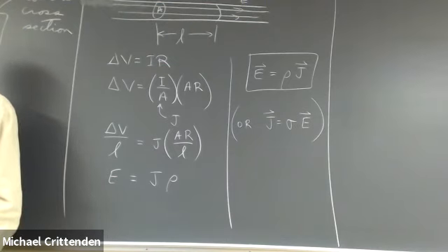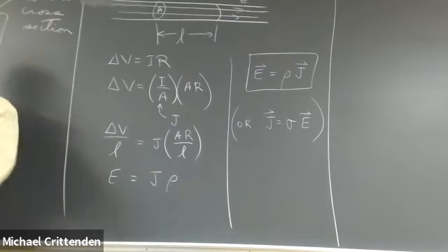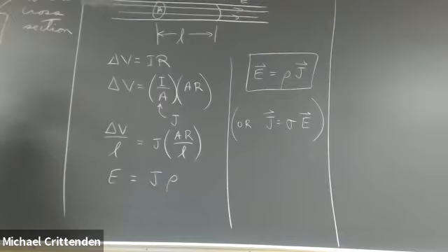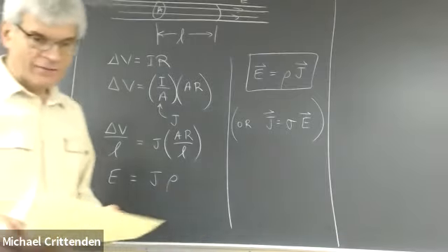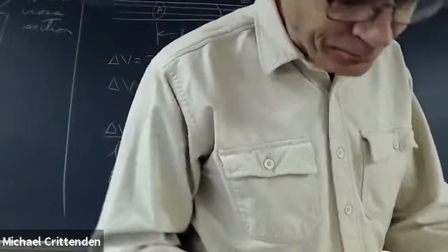Or maybe a more extreme example is something that's not really a resistor at all. A solid state diode is extremely non-ohmic. You apply a voltage to it in one direction and the current just goes right through real nice. You just take your battery and turn it around and the resistance is huge. The current hardly goes through it at all. So ohmic versus non-ohmic. Okay, so number 8, the toaster oven.